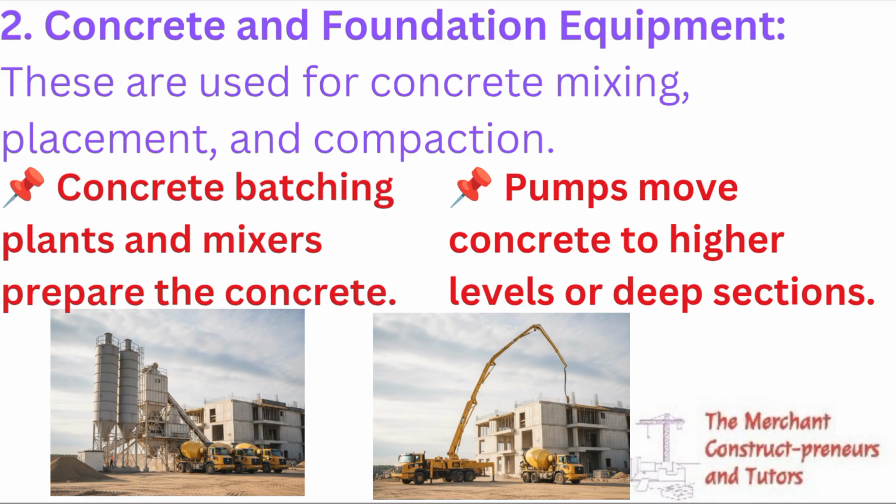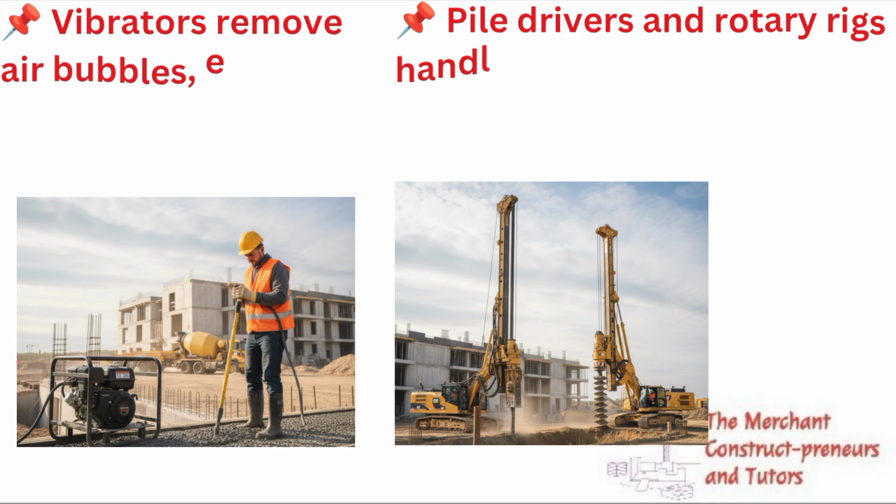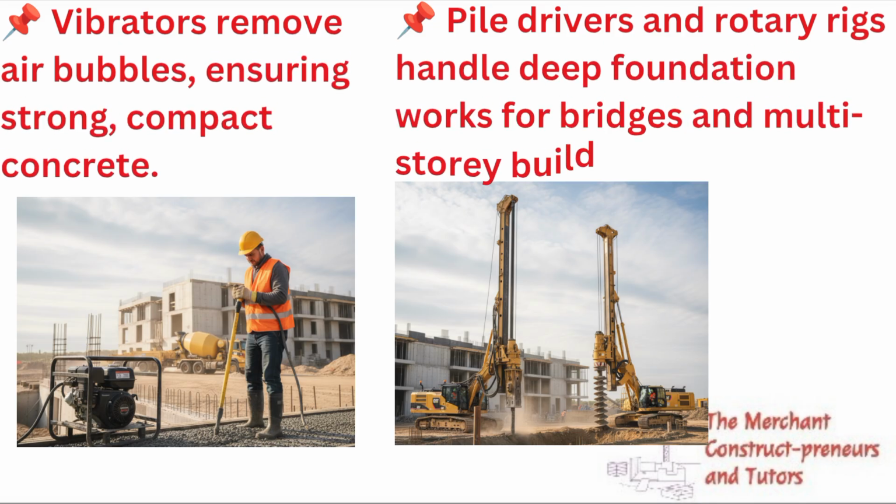Then the pumps, when taken to the site, pump the concrete to exactly where it is being needed, right? So the vibrators, after the concrete has been pumped there, remove the air bubbles and the air pockets in the concrete, ensuring proper compaction of the concrete.